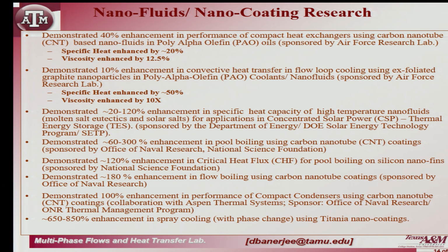And then in parallel we were doing some spray cooling experiments a few years later, where we used titanium nanoparticle coatings, and the heat flux went up by a factor of 6 to 8, or more like 7 to 9. Okay. So now the big question is, where is this enhancement coming from, number one, and why is the enhancement so lopsided? Why is it so distorted that your lower thermal conductivity material is giving you a higher enhancement? Okay. So we wanted to answer those questions.